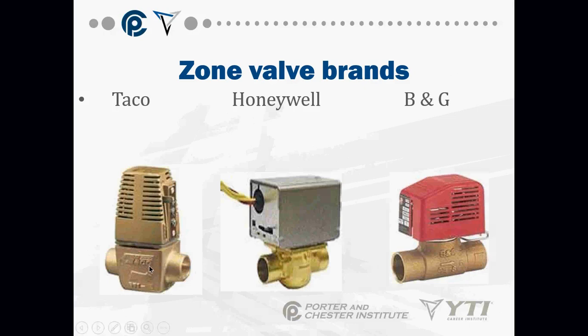Zone valves have to be installed in the direction of water flow. As you can see in this picture right here, there's an arrow. That arrow has to be in the direction of water flow. Zone valves are directional. If they are put in the wrong way, they are not going to open properly. You can see it here. There's an arrow right here. This is a little bit fuzzy, but it's there. Same thing with the Honeywell.